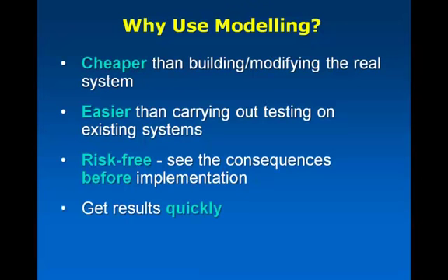And the other reason is, of course, you get results quickly. So if, for example, you were going to change your wastage at your wastewater treatment plant, and you wanted to see what effect that was going to have on the mixed liquor or the SRT, if you make that wastage change, it's probably going to take several days or even a couple of weeks before you fully see that system come into equilibrium. Whereas in the model, of course, you get that answer pretty much right away.